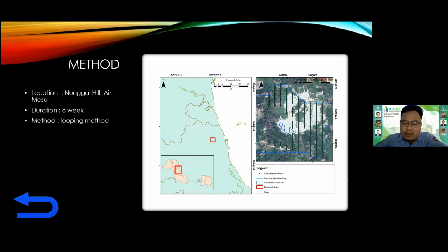Different geomagnetic values represent different kinds of materials. Granite stones may be determined from their geomagnetic values. This research is located on Bukit Nunggal and has a research area of 144.98 hectares, with two different ways of acquisition. One is using fixed points determined by the working plan map, and another is using random points. Both ways of acquisition have an acquisition distance of around 10 meters.